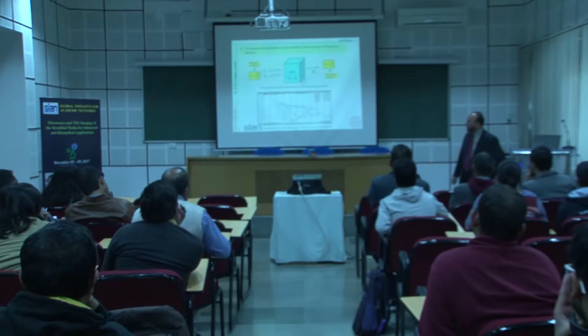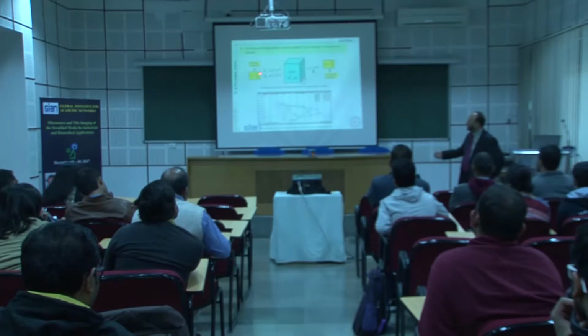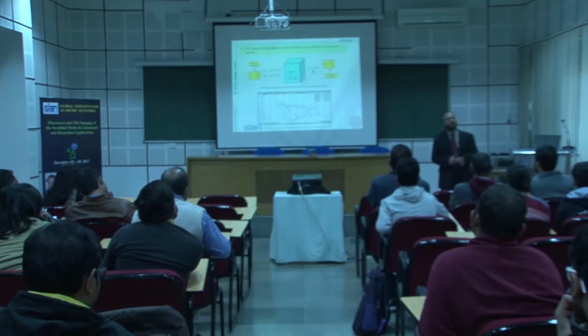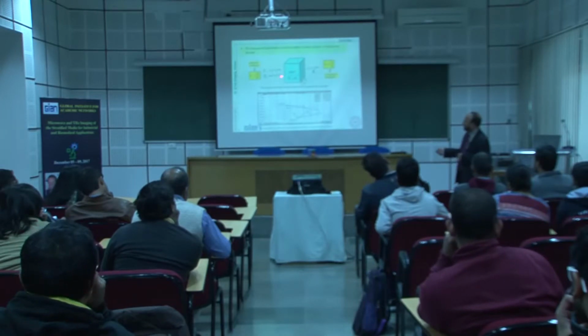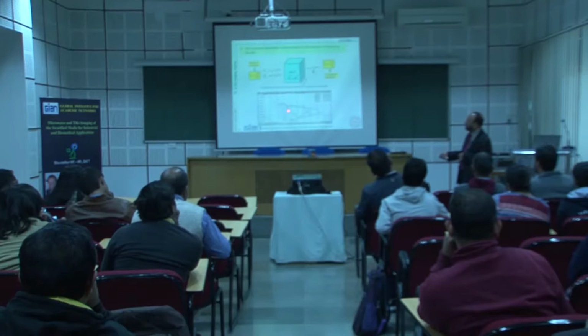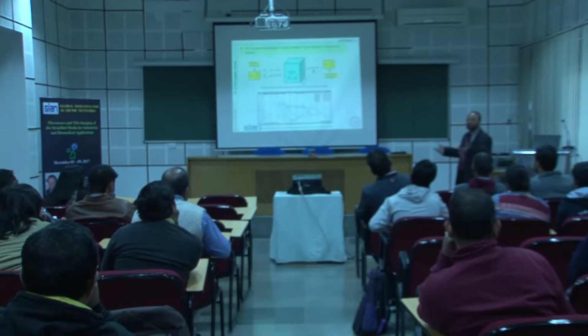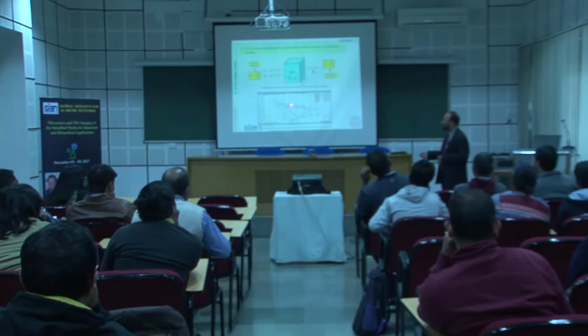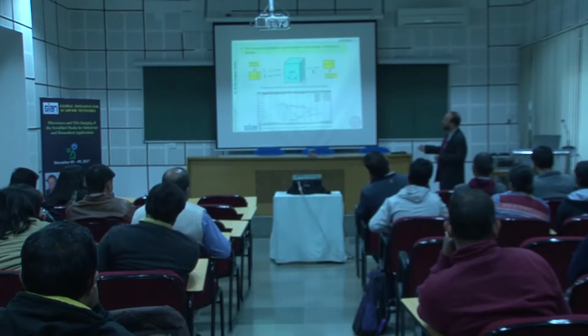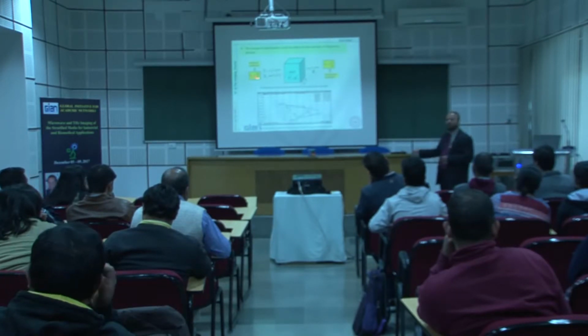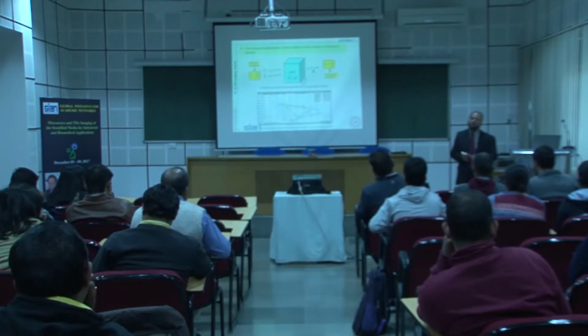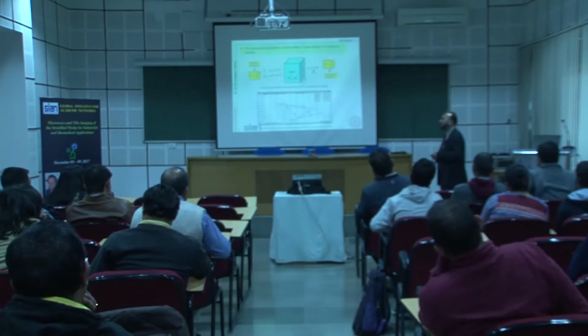For example, let's say I have this kind of block and I am exciting from this side, and I have an antenna which works at about 40 gigahertz, and a network analyzer. If this is quite thick, then I should be able to get many such peaks on the screen. From these peaks, I can see that the first peak corresponds to the first discontinuity between this and the background. If you know its dielectric properties, I can know its thickness. If you know its thickness, I can get the dielectric properties, without doing anything else. Maybe it's approximate, but at least it's very simple.